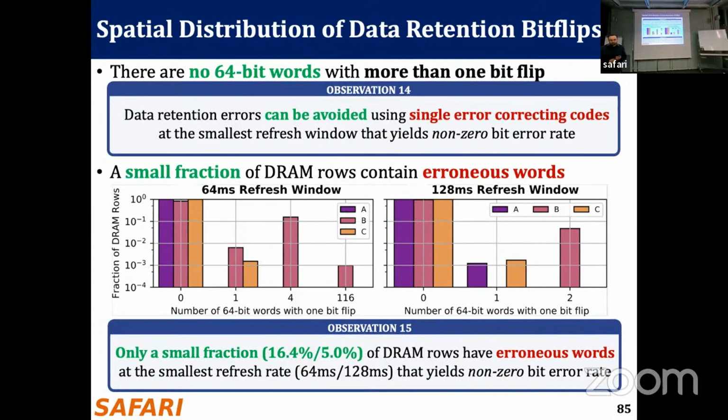So are there voltage levels where you get all 0-bit error rates, reduced voltage levels? Probably. I need to check that. You have the data probably. Yes, I should have that data. Off the top of my head, I can confidently say that at 2.4 volt, 2.3 volt, very close to nominal voltage, you don't see any bit flips. But I'm not sure how low it gets. I need to analyze it.